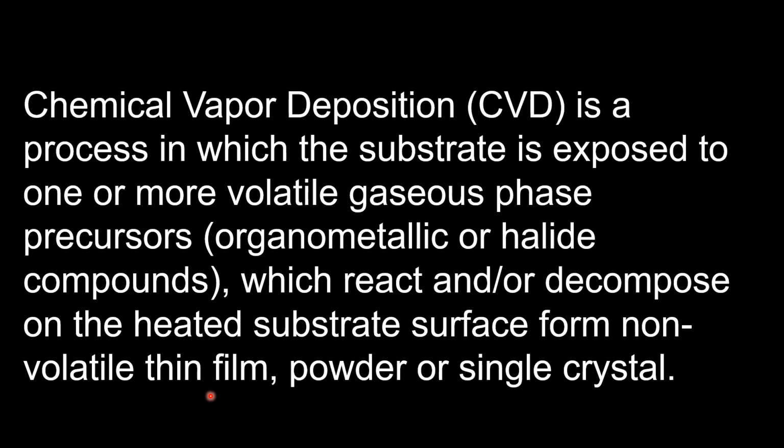Let's say you want to prepare a single crystal on the surface of a substrate by a CVD process. For this, you need to have a single crystalline substrate. That single crystalline substrate in a CVD reaction chamber acts as a prototype, or as a seed.